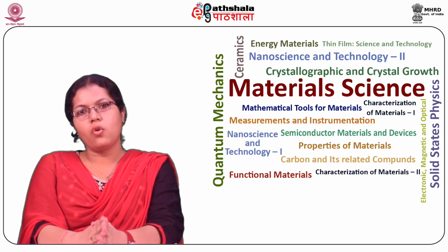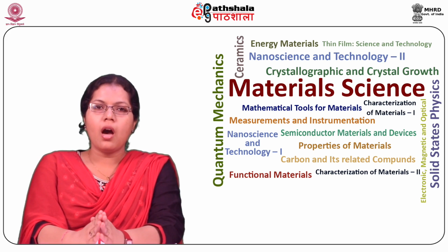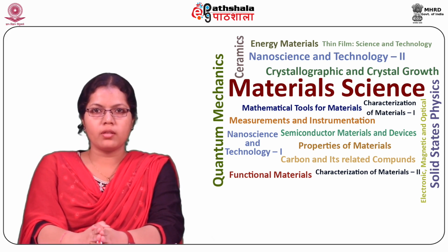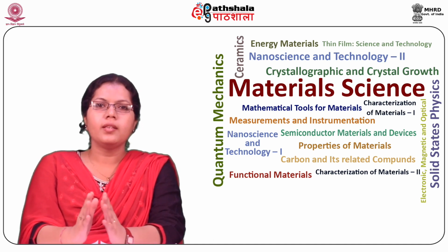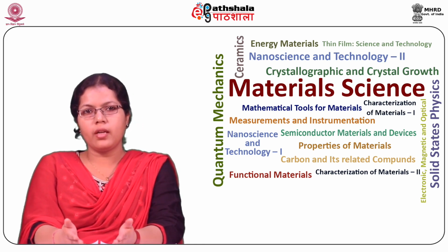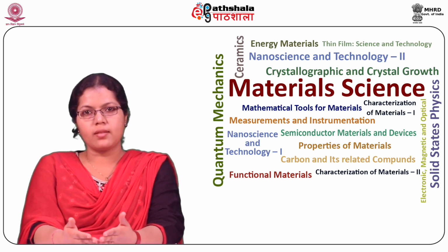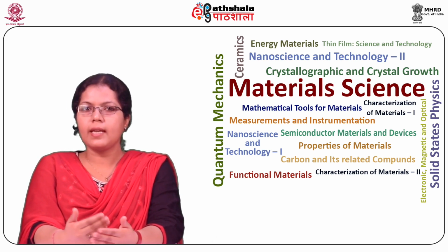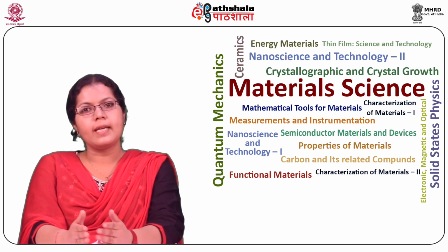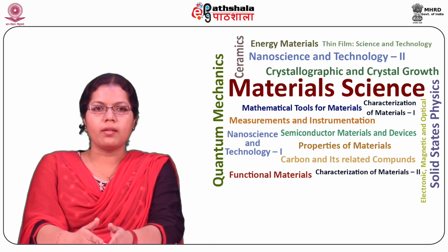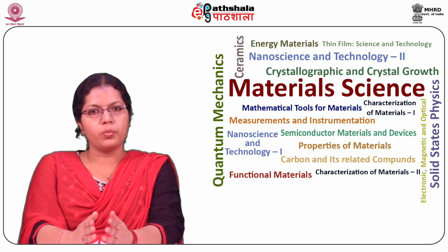Physical conditions of the transducers and also the measurand are very important for the selection of transducers. These must also be taken care of. First, the room or available space to mount the transducers is important. Second, whether the measurement is static or dynamic will also decide the type of transducers to be used.